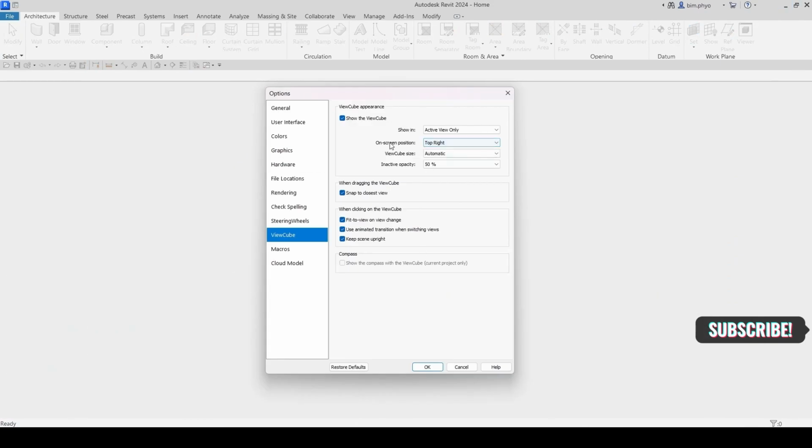Okay. The location is on screen. The position is top right here, top right here. And the ViewCube size is set automatically. If you don't want to see the bigger size, you make it tiny and small in here. You can set it in the option. In active opacity is 50%. You just make it the default.